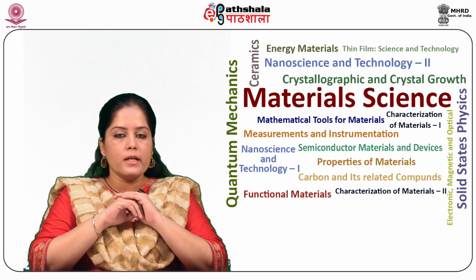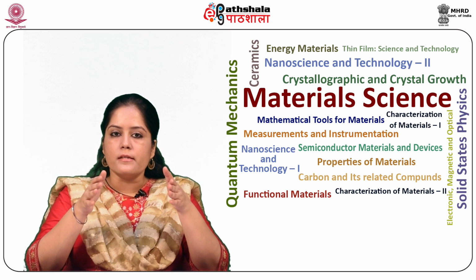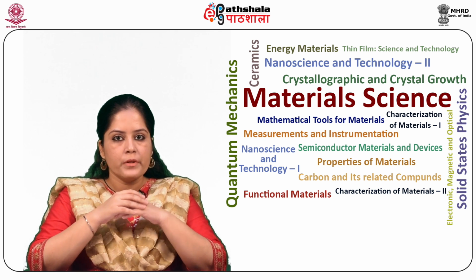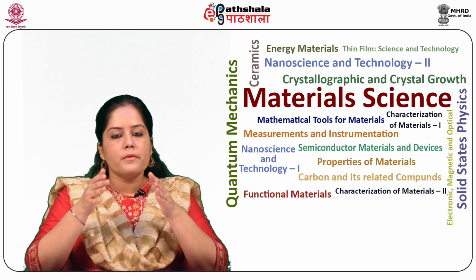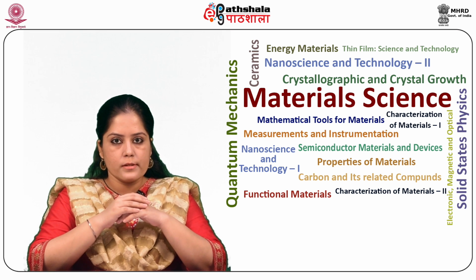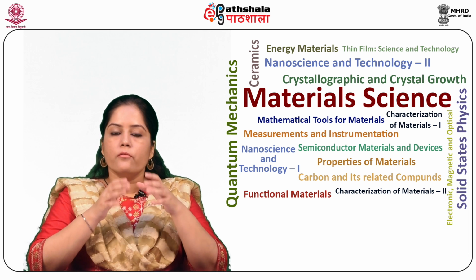Projection soft X-ray lithography, also called EUV lithography, was invented independently in the 1980s by research teams at NTT in Japan and at Bell Laboratories in the US, who were inspired by the availability of mirrors of reasonable efficiency at soft X-ray wavelengths, which is approximately from 4 to 40 nanometers. EUV lithography uses photons with 13.5 nanometer wavelength to expose wafers.